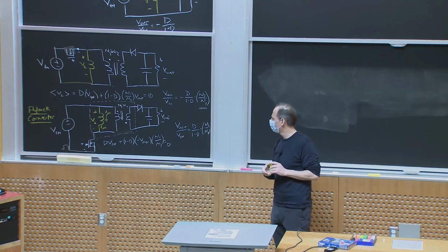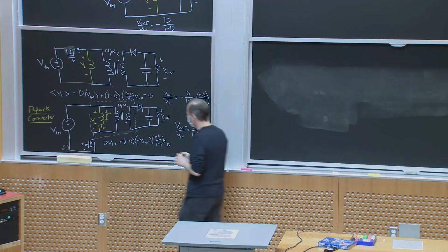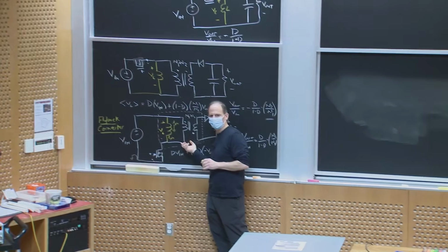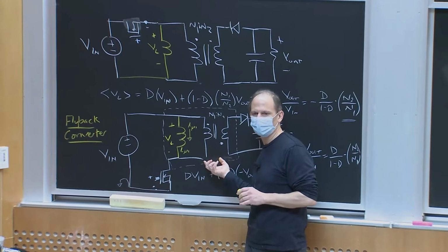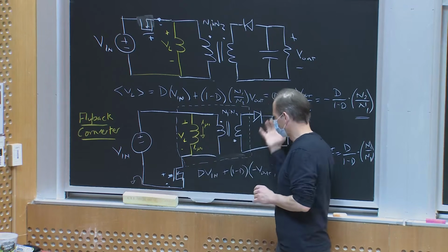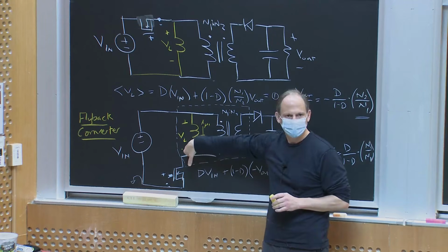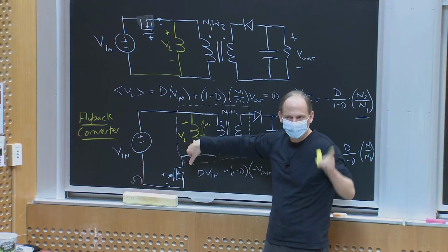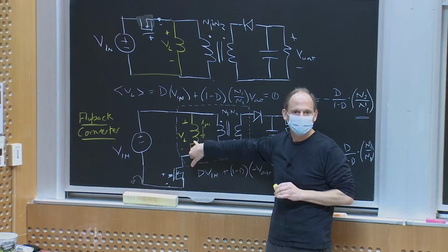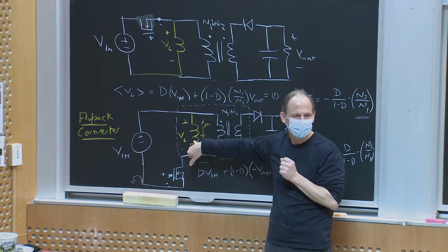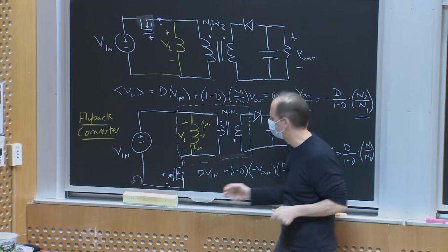How would I design the transformer for this kind of thing? Well, like an ideal transformer, I don't want any energy storage in it, right? The magnetizing and parasitic, I usually want it to be infinite if I can make it that way. But now, keep in mind that in this converter, this yellow guy here is our energy storage element, right? So if I'm going to store energy in it, I usually would like to gap my magnetic structure so that it can efficiently store that energy in a small space, right? Because we put the energy storage in the gap.